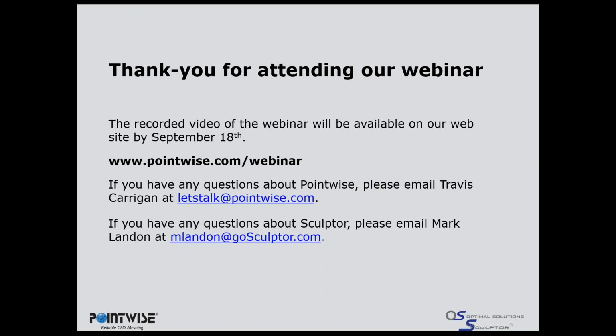We have the option to actually calculate the cell quality during the morphing process, and it can report back to you what that is. But it helps to have a little experience with Sculptor so that you create the appropriate shape change variables and the adjacent control points so that you have enough room or volume to have a smooth deformation out into the flow domain.